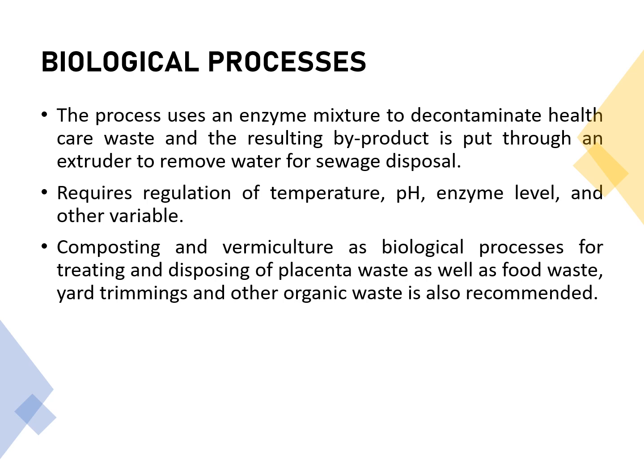Another method of treatment is through biological processes. This one uses an enzyme mixture to decontaminate healthcare waste, and it requires regulation of temperature, pH, enzyme level, and other variables. Examples of biological processes are composting and vermiculture for treating and disposing of placenta waste, as well as food waste or kitchen waste, yard trimmings, and other organic wastes.